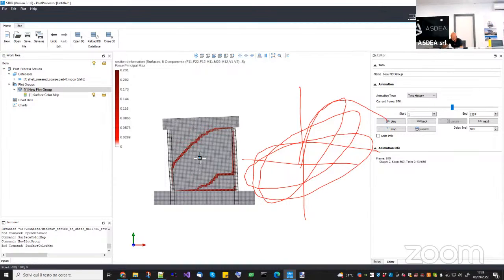Yeah, no, what I say in fact is that when you look at it without testing it, it looks like just a better hysteresis loop, but it's not so important. Instead, it is very important, because from what I've seen, the more cycles you do, the more important it is, because otherwise you accumulate too much damage. In the real case, when I have pinching, I start damaging when I reach the previous point. In my case, I will start damaging much before. So basically, I'm stressing my structure more and more if I do not recover all the plastic deformation.